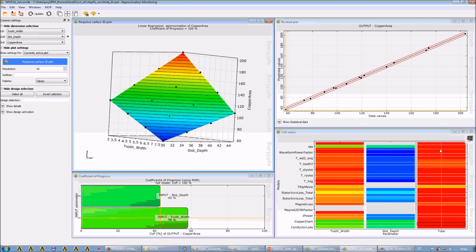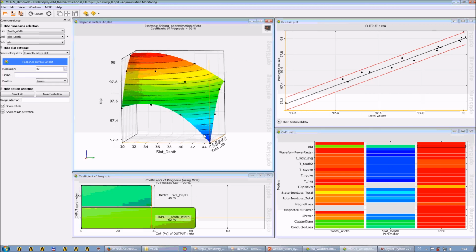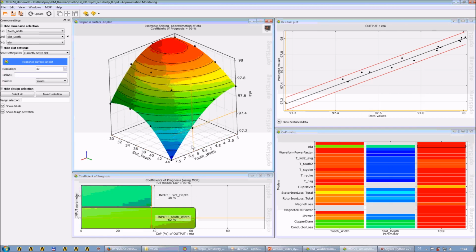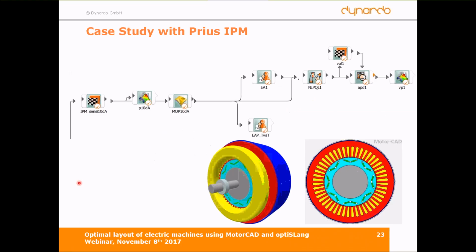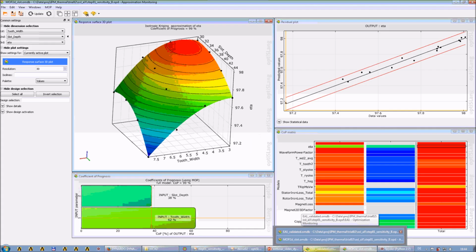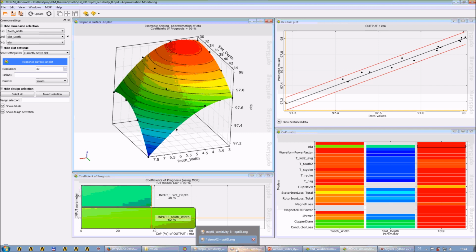And if you look at a quantity like the efficiency, you can see here the nonlinear response. And it's just 2D. In this two-dimensional world, we can use these 16 design points, 4 by 4. We can use this full factorial scheme to get a pretty good feeling of how the system reacts, even how the system reacts non-linearly. But how about many dimensions? How does it look like if I'm varying many parameters?